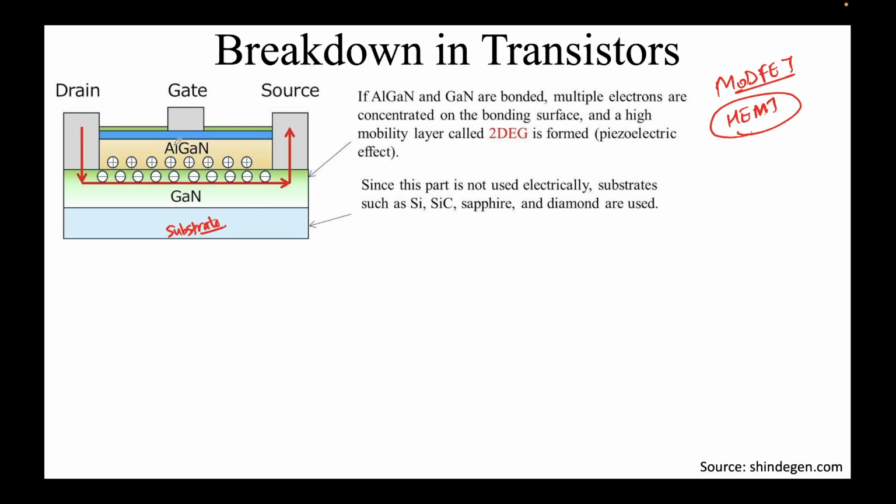Please remember, in the MOSFET or MOSCAP, we had to apply a positive gate potential in order to have a negative sheet of electrons. Here, even at 0 gate bias, this negative sheet of electrons is already present. So let's say we are talking about Vg equal to 0. The sheet of electrons is already there. The plus that you see, you can just assume is to balance the charge, because essentially this structure is electrically neutral, okay? And this drain, which is again N plus doped, as I told you in the case of a MOSFET, right?